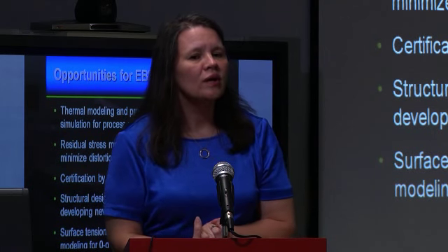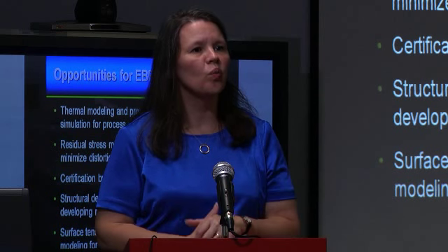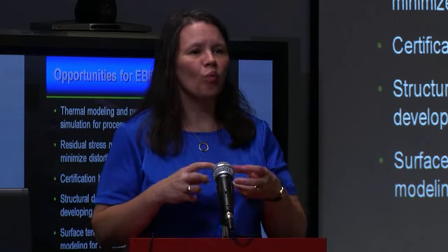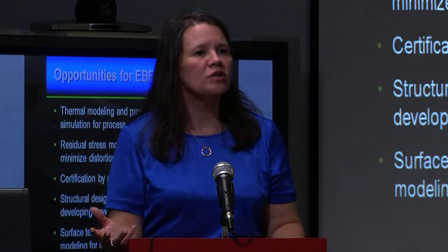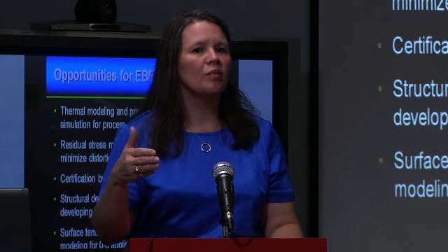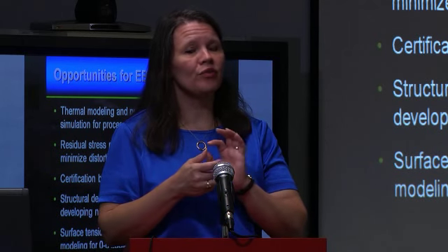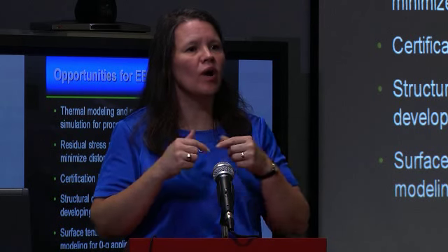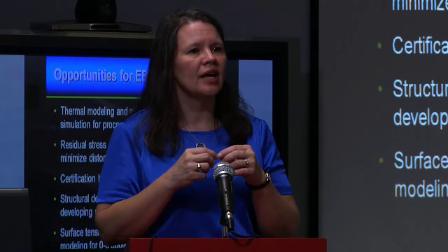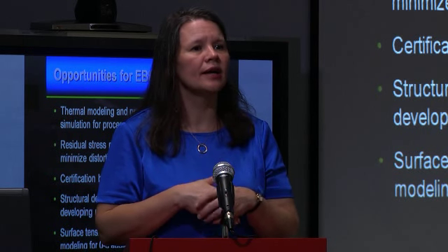So the question is, with wire welding, oftentimes you can get snags and wire buildup in the wire feed lines, and what are we using to try to eliminate that. One of the things is precision, and we've designed some supports that help to guide that wire all the way so that there's not as much opportunity for it to create a little bird's nest in there.